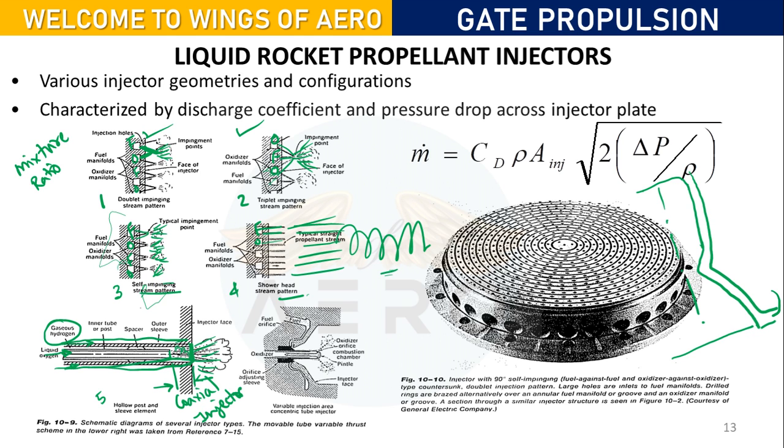From here they will feed liquid hydrogen, or whatever the fuel may be, in liquid form. It flows through the outer jacket. Because of the high amount of heat produced in the nozzle, it transforms from liquid to gaseous form. That preheated gaseous fuel then feeds into the injector. So that's why it is written as gaseous hydrogen. Clear?